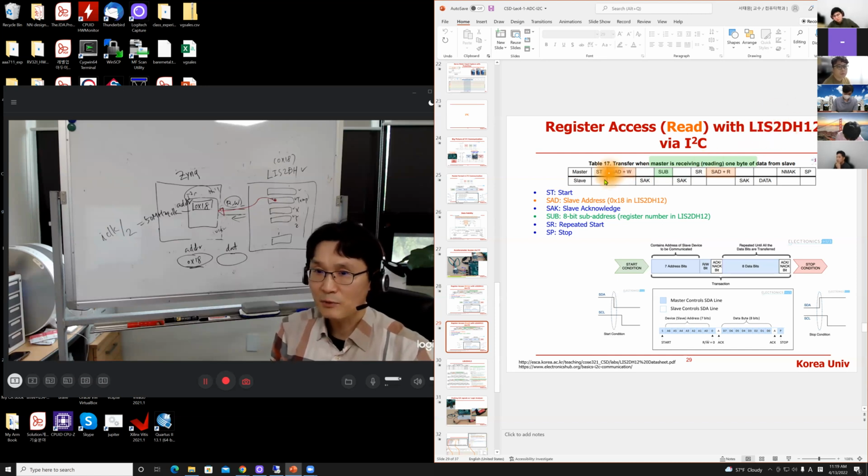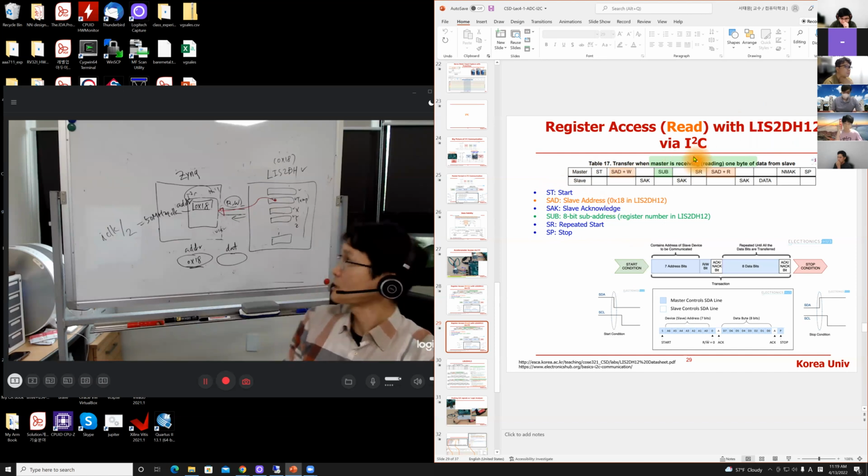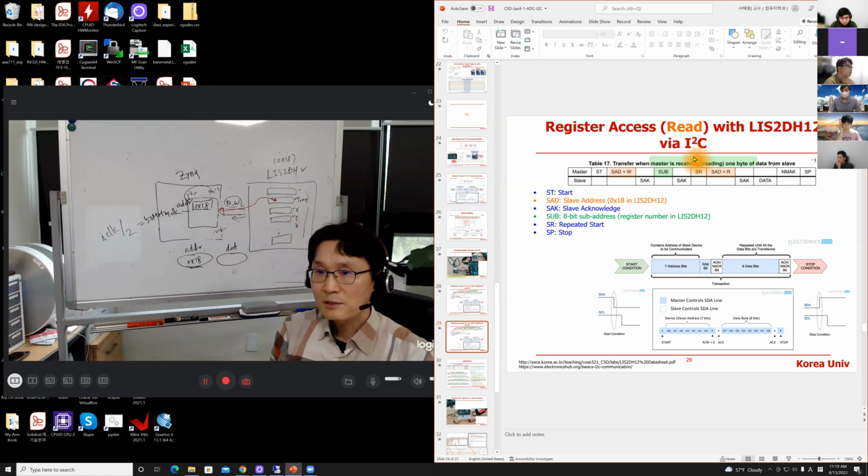Okay, so look at this. What is that? The acronym. There are acronyms. ST, start, right? Start condition, so obvious. Then comes the slave address. This one, 0x18, right? Slave address, and with write operation. Strange, right? You are reading, but you have to write. Write what? But it is a write transaction.